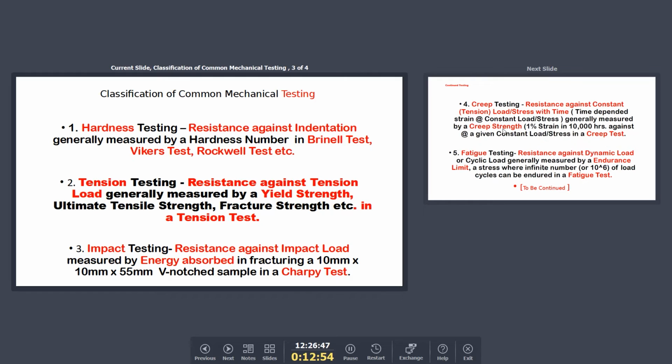This is a very important kind of test, particularly in the modern field, because man is continuously using low temperature for different uses in freezing, and in the transportation of ships through polar areas, icy conditions, in fact. So when we go to the chapter on impact testing, we will discuss this. And the most common test procedure, now internationally accepted, is the Charpy test.